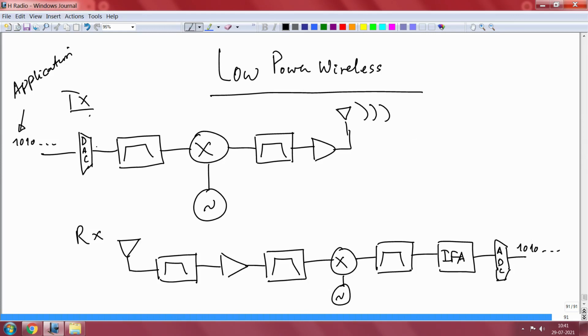Now, after you get it into an analog signal, you have to apply an appropriate filter to ensure that certain frequencies are not transmitted, and that only those frequencies in which the data is available are used, because now it is an analog signal. It will be associated with an amplitude and a frequency component. So, essentially you will have to pass it through a filter and then you have to up convert. So, this is your mixer. Once you mix it, it becomes an up converted signal here.